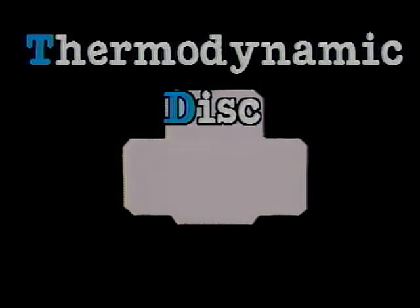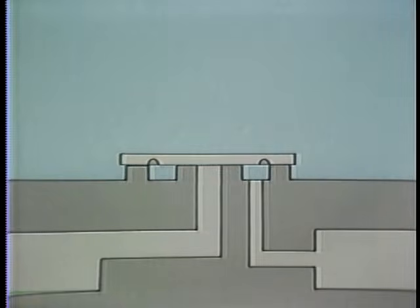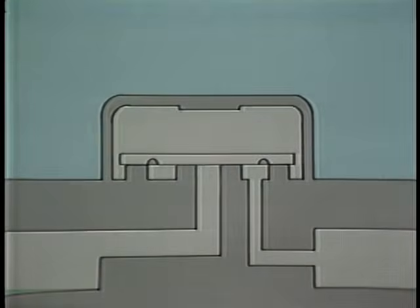The disc trap contains only one moving part, the controlled disc itself. When the trap is closed, the disc is on the seat, sealing both the inlet and the outlet orifices. The area containing the disc is called the control chamber. It is a relatively large volume space with restricted inlet and outlet ports. It is the change of state which occurs here that normally controls the opening and closing of the disc trap.